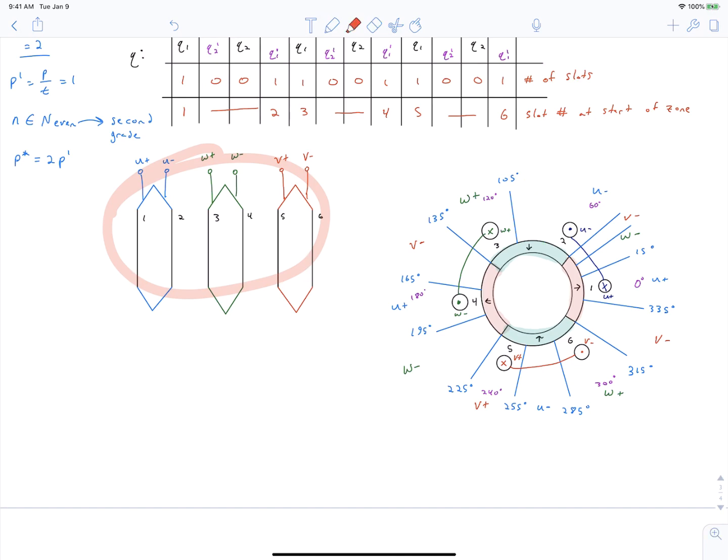So it's crammed the V minus and W minus coil zones in before the U minus. So it's shifted the span to be very small for these phase zones. And then we regroup over here at W plus is where we expect it to be.